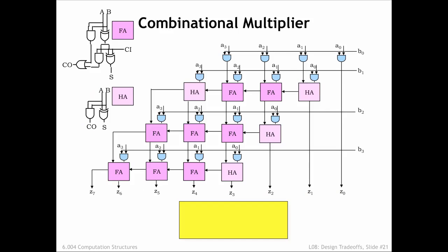Here's the schematic for the combinational logic needed to implement the 4x4 multiplication, which would be easy to extend for larger multipliers, we'd need more rows, or larger multiplicands, we'd need more columns. The m times n 2-input AND gates compute the bits of the m partial products. The adder modules add the current row's partial product with the sum of the partial products from the earlier rows. Actually, there are two types of adder modules. The full adder is used when the modules need 3 inputs. The simpler half adder is used when only 2 inputs are needed.